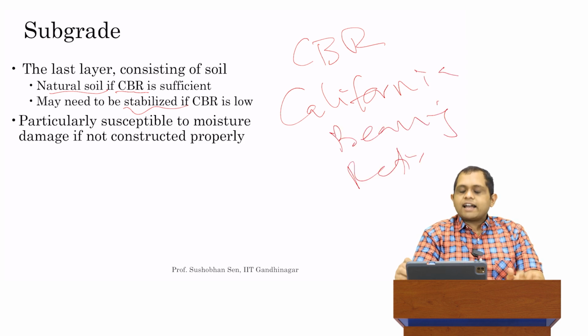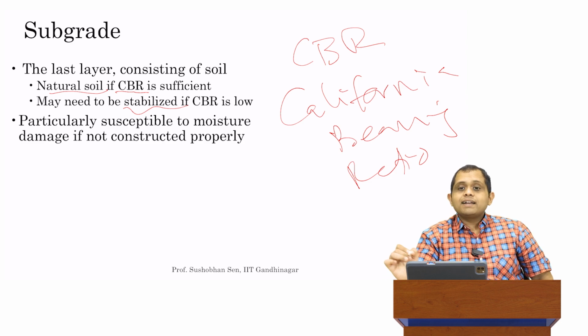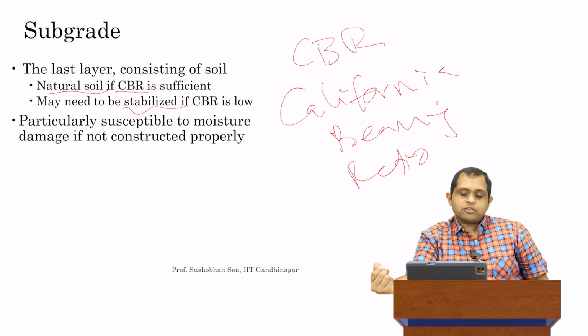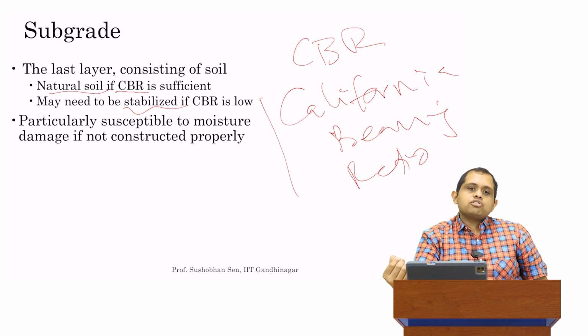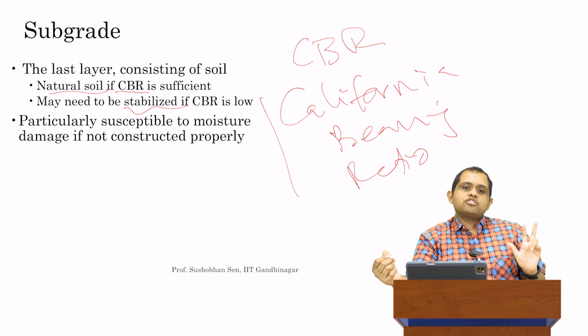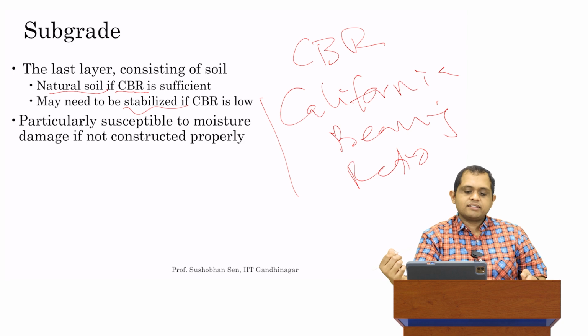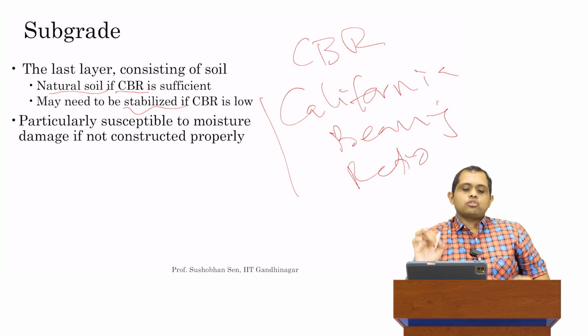So it's actually not used all that widely currently in pavement design analysis, as you will see in subsequent lectures. But for historic reasons, it's almost 100 years old as a measure. It is an empirical measure of the strength of a layer. It's almost always used only for a subgrade layer. We'll talk in later lectures about what exactly that means and how we can quantify it in more mechanistic terms. But it's an empirical measure of strength.